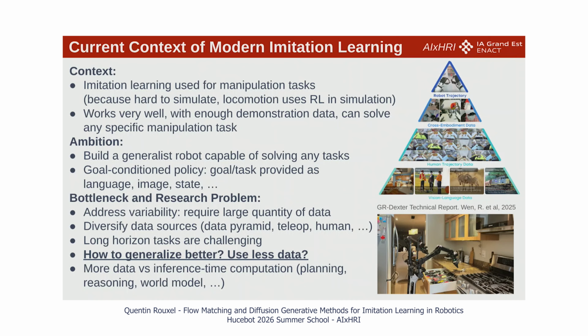So there have been a lot of ideas of how we can scale this data, because collecting teleoperation data for every single task that exists requires a huge amount of resources, which is usually very difficult to do. So the last 2 years of research were about how to use other kinds of data to train this model to be able to scale up. Like with LLMs, which were trained on internet-scale data, a huge amount of data, the whole idea in robotics right now is to try to find other sources of data to train these models. Some ideas are using cross-embodiment data, so not only data that comes from the robot you want to use, but from other kinds of robots, maybe different humanoid robots that collect data for a bimanual robot or the opposite.